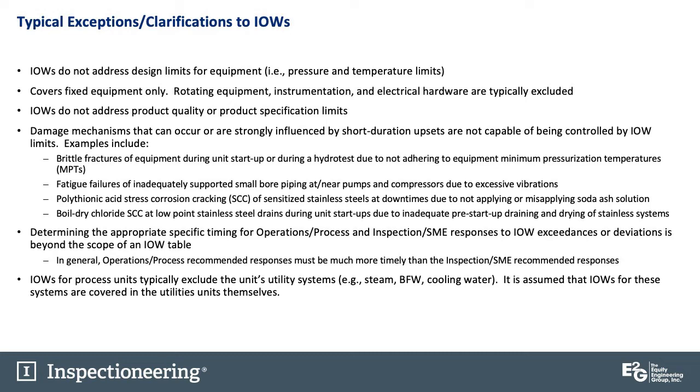Also, damage mechanisms that can occur or are strongly influenced by short duration upsets are not really capable of being controlled by IOW limits. Some examples of that are brittle fractures of equipment during unit startups or during a hydro test due to not adhering to a minimum pressurization temperature.